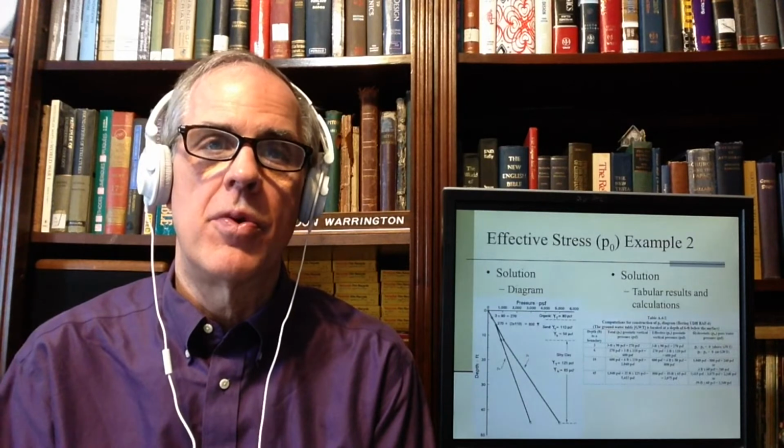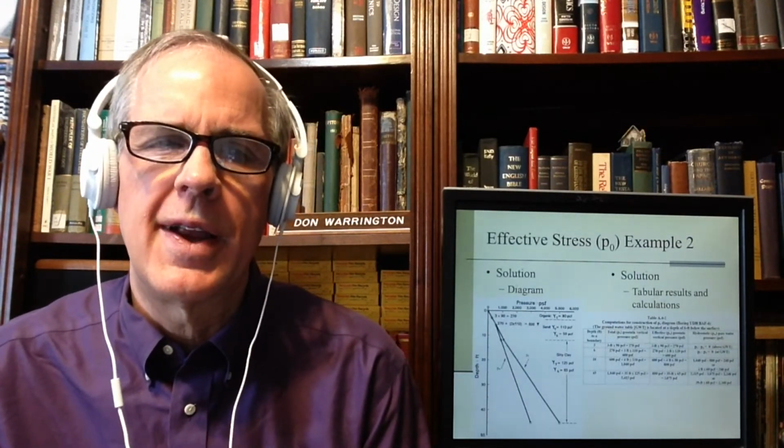And normally speaking, a cone plot will include the pore water pressure. And it will also usually include a little broken line for the reference pore water pressure. Well, the reference pore water pressure is Z times gamma water from the top of the water table. And you'll see those diverge, and there are various reasons why. But again, for our calculations, we're going to stick with doing it Z times that for most of the problems that you get from me, because that's the way we want to start.